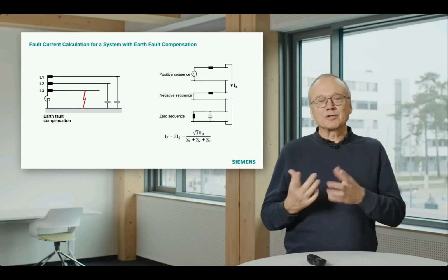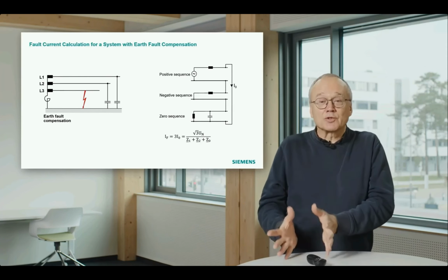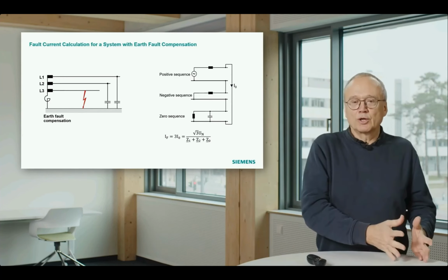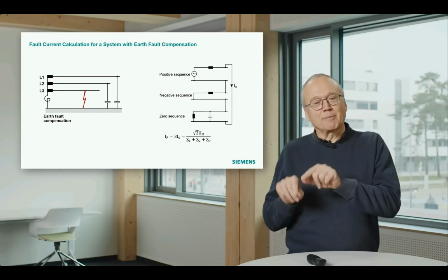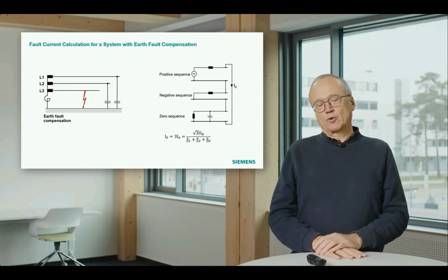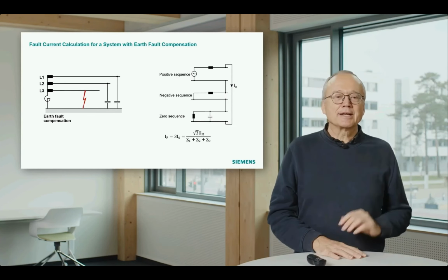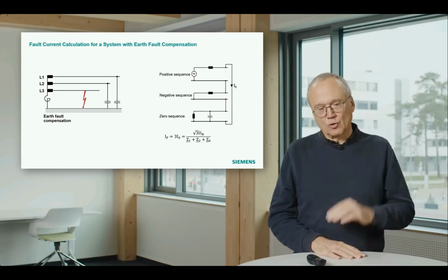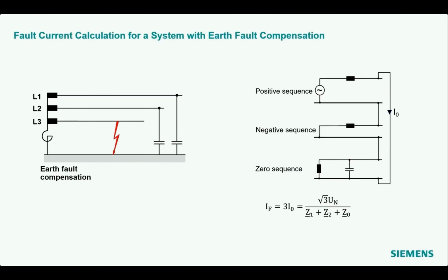Now the interesting question is, of course, that is the zero sequence world. Where can this inductance be in the real world so that it shows up at that point in the transformed world? The result is we can put it into the star point. That is shown in the real world diagram on the left side. There you see this coil, a big inductance, connecting the star point to ground.